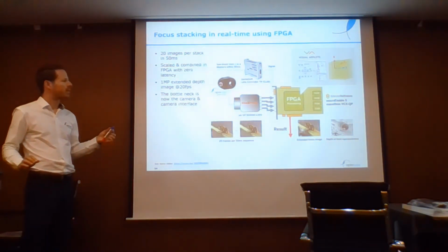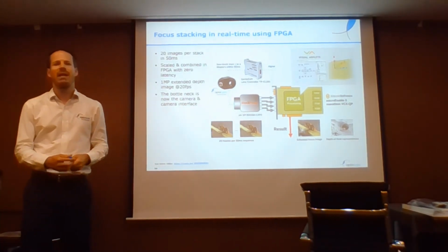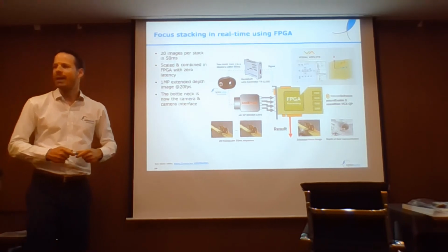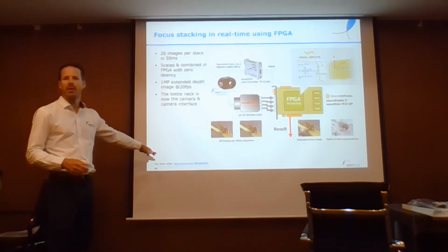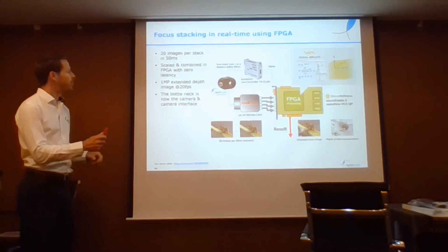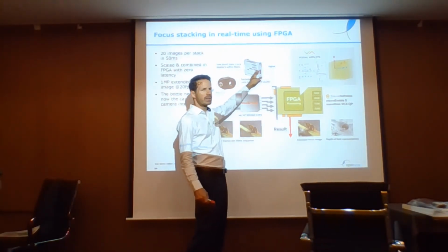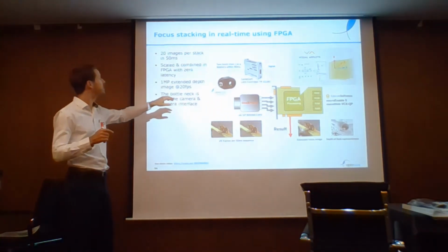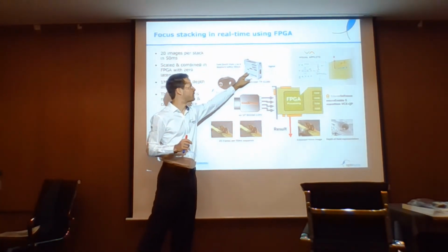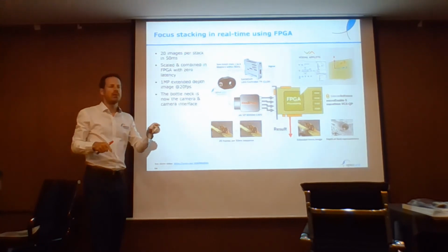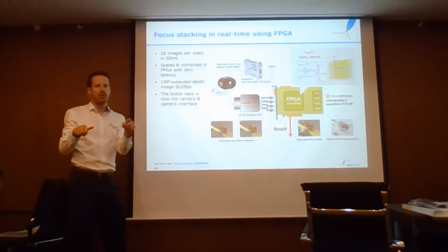Now, Silicon Software is a German company who makes frame grabbers. Their frame grabbers have a pretty fast FPGA on them, and they did a little demo with us. There's actually a YouTube video if you want to look at that as well. The point is that the FPGA sends a trigger signal to the Gardasoft driver 20 times per second. So every 50 milliseconds, you get a trigger. The Gardasoft driver makes a sawtooth waveform. So within 50 milliseconds, the lens goes across its whole tuning range, back to 0 and goes again.